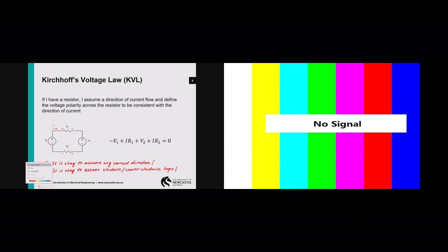So the first step, I determine that I'm going to use KVL and Ohm's law, right? So KVL, draw a loop first. Okay, let's draw a loop. From drawing a loop, I can also label the voltage across resistor 1 as V3 maybe. V3. Voltage across resistor 2 as V4. Okay? So going really slowly, I'll travel from this starting point here, going up, negative V1, okay? Hitting this one, we have plus V3.